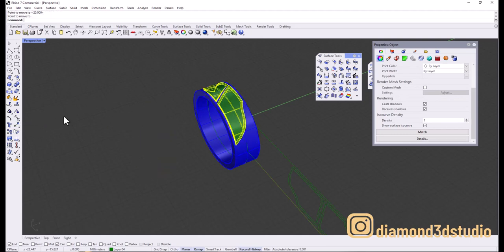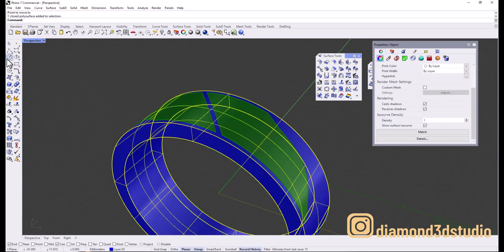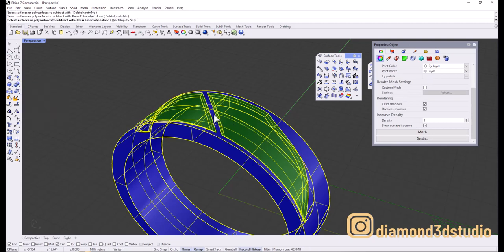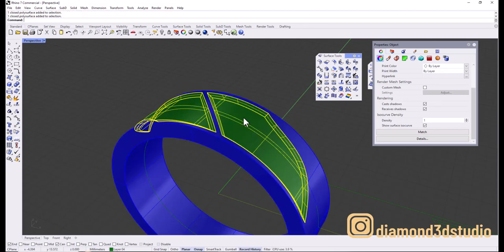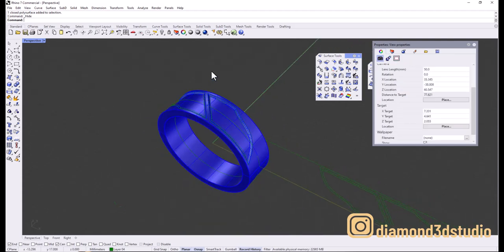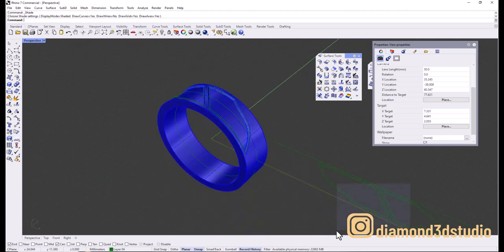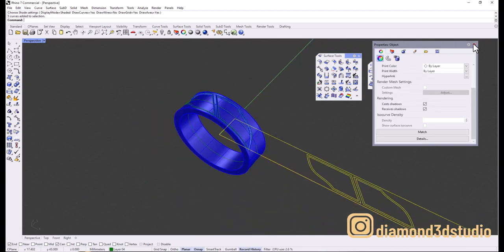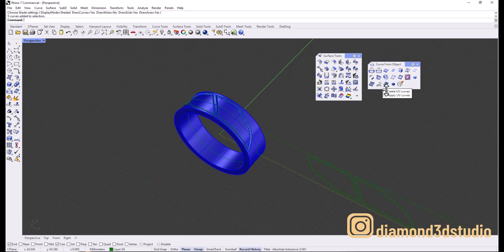So move it back 20 mm away, and just do a Boolean difference with the delete option no. Okay, because at times you need this cutter till the end of the completion of your ring, so I would suggest to save it, group it and save it, and that's it, you have it ready. So this was a UV option which we did over here.